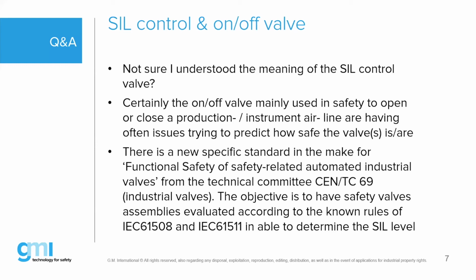So, in honesty, Tino, I don't know about control valve, but we do have requests, and there are not many, but when you look at the IO counts of several projects, they are requesting SIL rated analog output card, where the analog output is driving a control valve. Correct. But there you must talk about the application for it. You talk about the analog output. I mean, the majority, 90% of all safety loops, maybe 95% worldwide, work through a digital output signal. But very few are there also. So there must be some application. Yeah, you start, you stop, you open, you close.